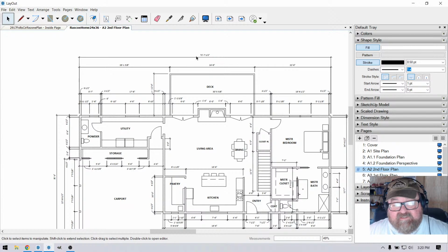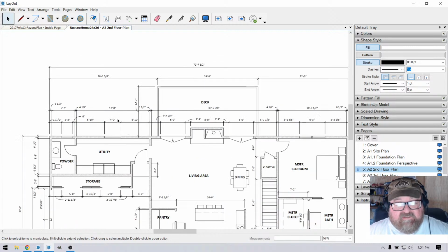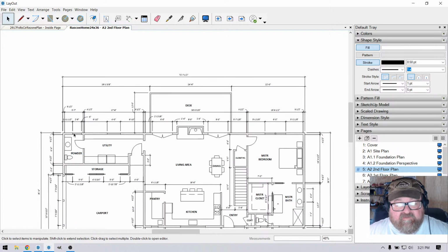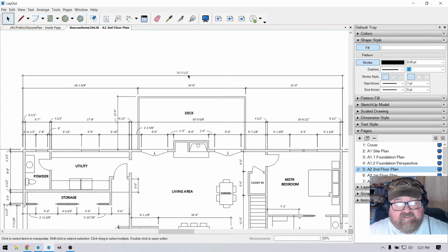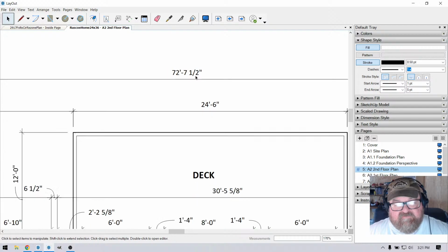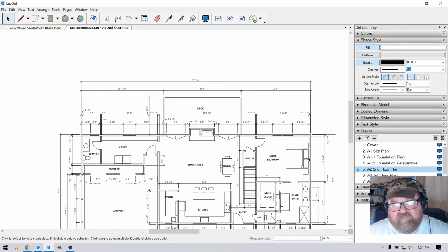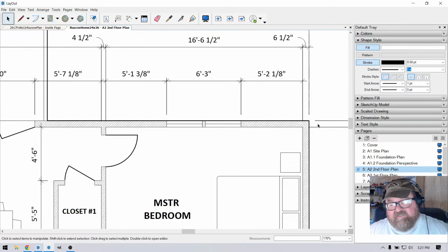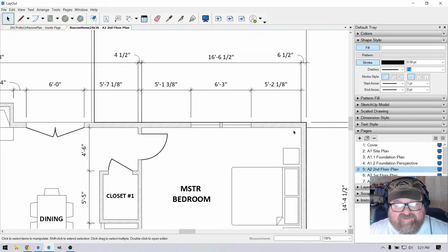And I dimension this line. This one's confusing enough because we actually had to move the footings on this one. We made it bigger, and so I got this kind of weird dimension. I don't like these weird dimensions, but you see, right off the bat, the framer would say, what is that ½ inch for? Are you trying to tell me that's the house line? You see, it just causes all kinds of problems.